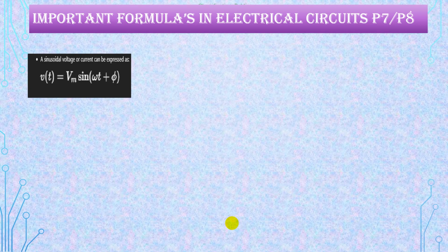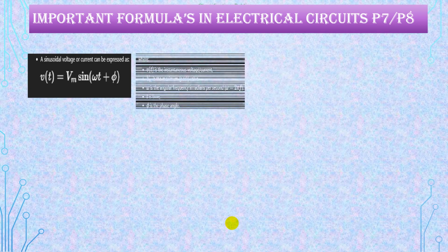For the capacitance it is quite the opposite. The current will lead the voltage. The current will start first, then the voltage. Or we can say the voltage lags the current. In inductance, the current comes later than the voltage. In capacitance, the voltage comes later than the current. So it is quite opposite, lagging and leading. We have to check.